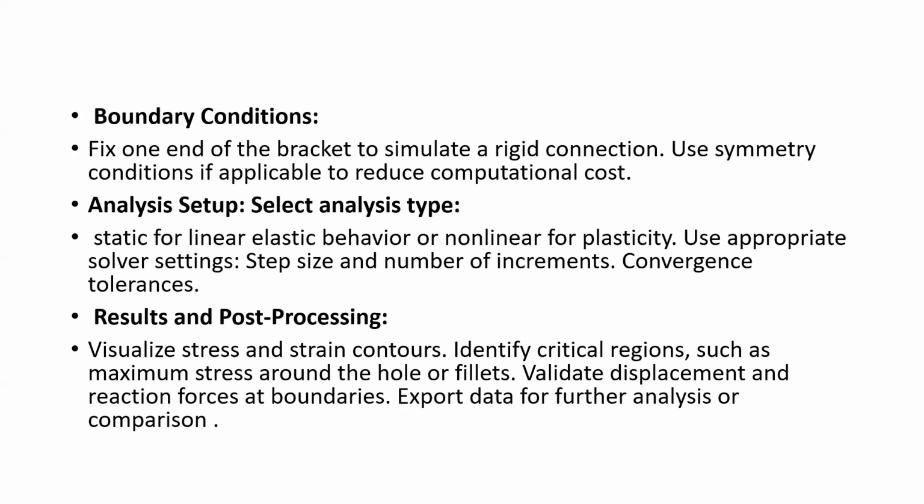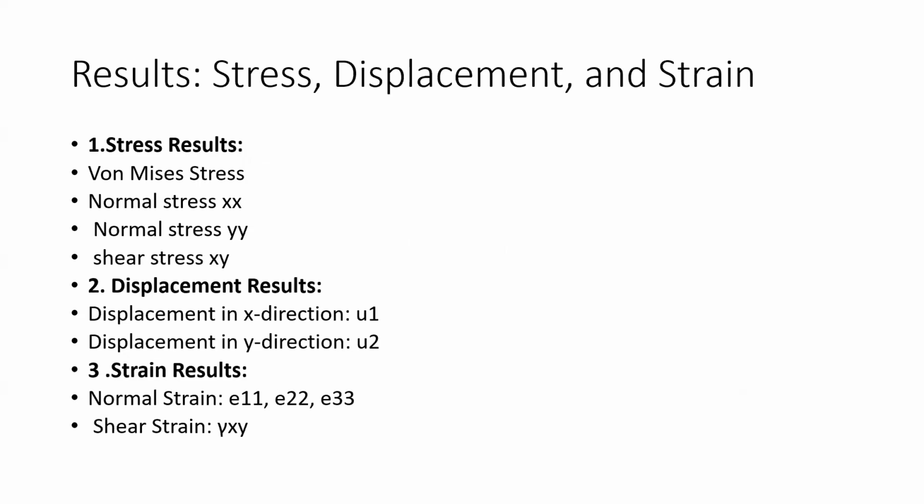Visualize stress and strain contours, identify critical regions such as the maximum stress around the hole or fillets, validate displacements and the reaction forces at the boundaries, export data for further analysis or comparisons, and then go to results. We can see here results like stress, displacement, and strain.